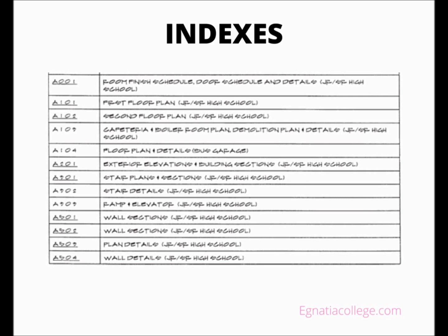Some architects indicate levels of drawings by using a series within a range to designate a level. For example, 100 through 199 might be reserved for foundations. 200 through 299 might be floor plans and elevations showing the overall superstructure. And 300 through 399 might be roof framing. This system is usually quite easy to spot by studying the index briefly.